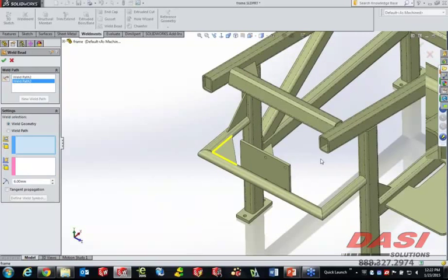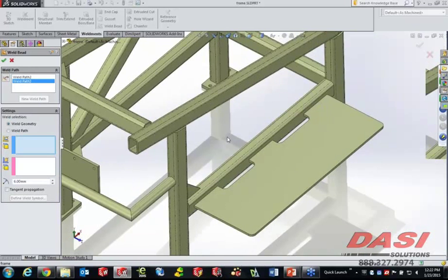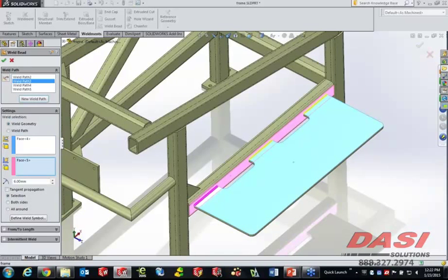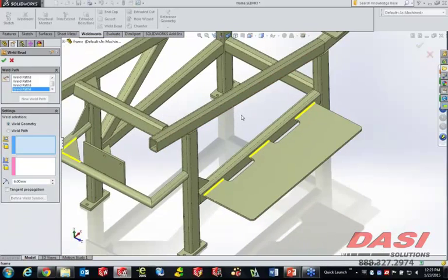So over here's another one that was a little bit more of a challenge, user interface wise, before: the selection between this part here and this part here. Now these have kind of a stitch in the way that they intermittently touch, but it actually creates three individual weld paths that show up between these two selections. So single selection, but a lot more output with a minimal amount of input. Let's go ahead and do another new weld path.